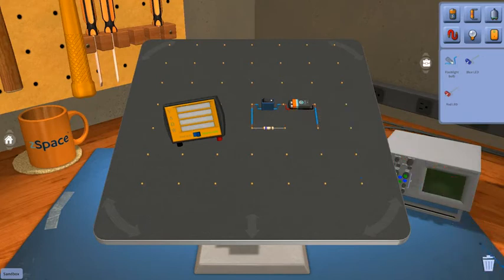But just to give you a quick idea, let me switch this motor out with this LED. And thankfully, this resistor does fit within the LED's requirements, but it's still not turning on, even though the switch is on. Oh yeah, the polarity requirement. So I'll right-click to pull up this object's context menu, then I'll flip the polarity, and there we go.